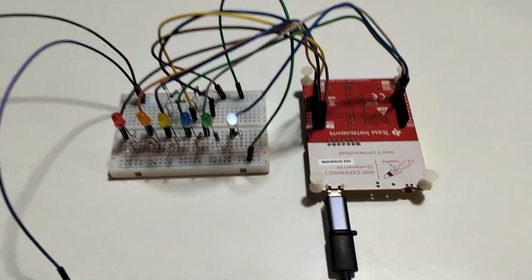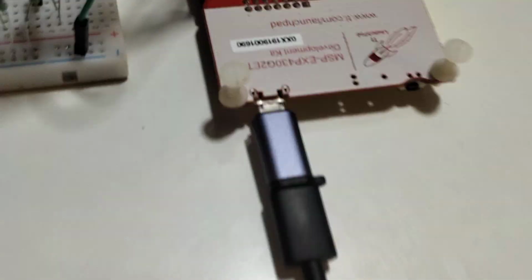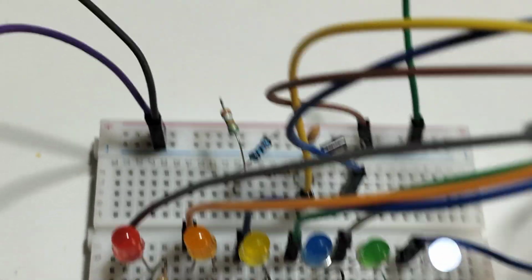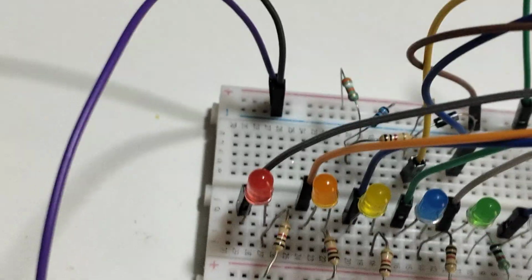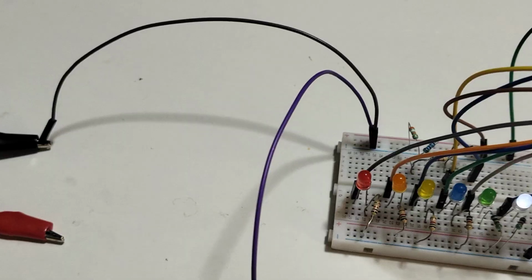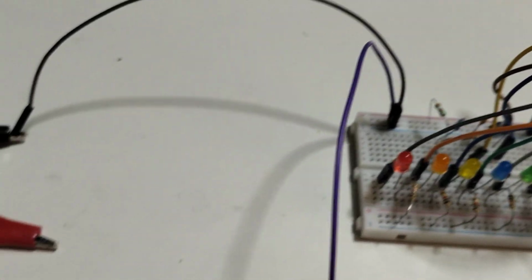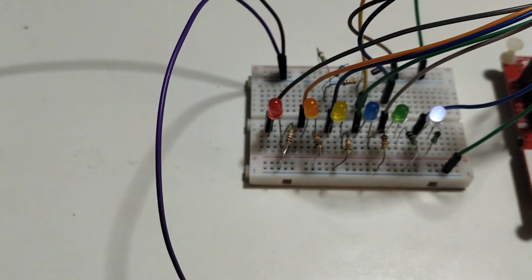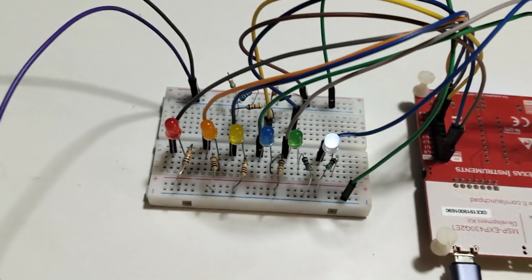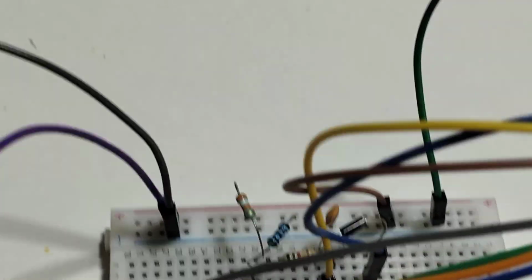So this is the setup, and you can see here that's the MSP board, the development board, and I have it plugged into my computer. And this is just the small circuit here. Basically, as I said, we're going to be measuring roughly a 12 volt signal. That's going to be the maximum voltage, maybe 13 volts. Of course we know the ADC range is maximum 3.3 volts, and here we are using a 2.5 volt reference, so even lesser. So of course you have to use a resistor divider or you will destroy your microcontroller.